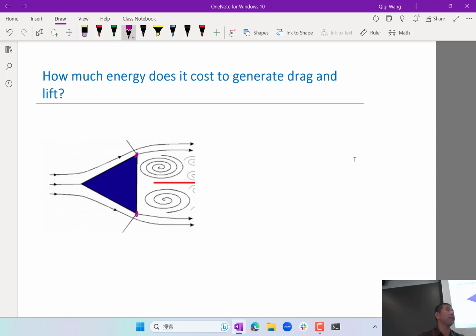And we'll talk more about flow separation later on, especially flow separation around not sharp angles but smooth objects. But it is actually intuitive, right, for flow to separate around sharp angles like that, right? And we'll look into why that is the case later when we look at boundary layers. But for now, it is sufficient to know that once you have a sharp edge, the flow separates.